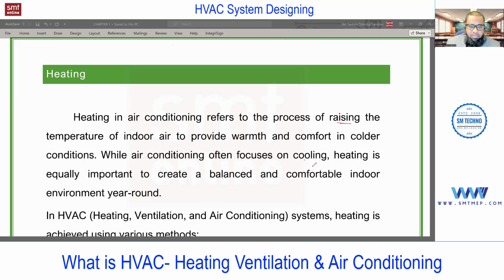So in short, heating is providing or increasing the heat to raise the temperature to maintain the standard temperature in winter. If the temperature is less than the standard temperature we discussed on the previous page, that is a set point you can consider. If the temperature is less than that, heating is required. If the temperature is more than that standard, then cooling is required. So with that set point we can decide when cooling or heating is required.